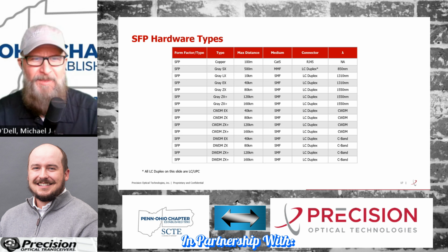I like it. That last column there, the lambda signal. So obviously for copper, we're not going to have an optical signal. SX, anything short reach, is going to be 850.